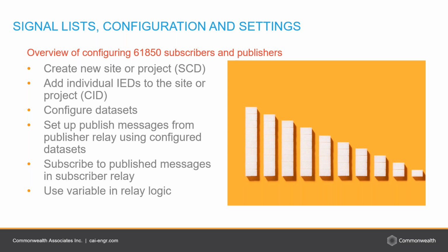And when you do that, it creates a CID file for each one of those individual IEDs that holds this configuration information. After your IEDs are added to your site or project, you have to configure data sets. And these data sets are user configurable.